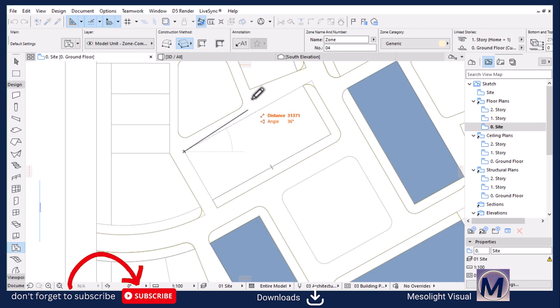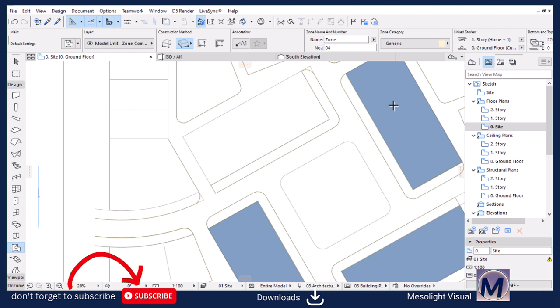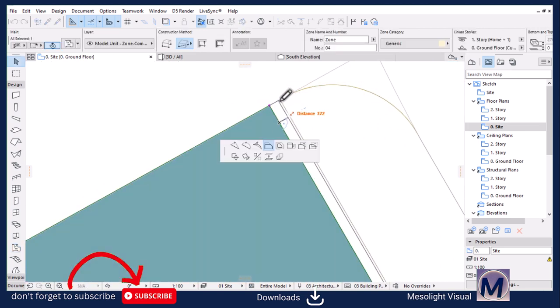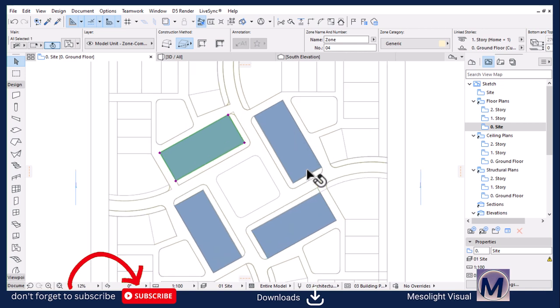To repeat the last operation, guys, I think you've been wondering how I'm managing to continuously go on with the tools or the operation. It's because of the commands. For example, I've been working with the zone tool. If I want to repeat the previous command with the same parameters or the same settings, you just hit W. It will activate that, and then you just continuously do your tasks. It's important because it speeds up the whole process instead of going back to the tool palette and going back and forth. That will take a heck of your time.